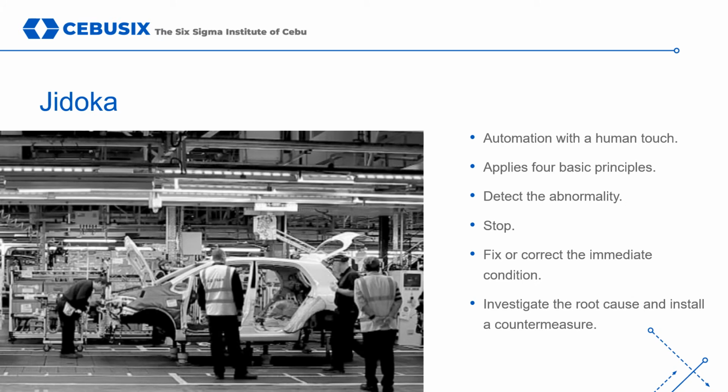Jidoka is a principle that creates control of defects inside a business process. Instead of identifying defects at the end of the production line and attempting to trace errors back to the source, Jidoka demands that a process stop as soon as errors are detected, so improvements or troubleshooting can happen immediately. For Jidoka to work properly, machines are often equipped to recognize bad outputs from good outputs. The machines are also equipped with a notification of some type to spark human interaction in the process when things go awry.